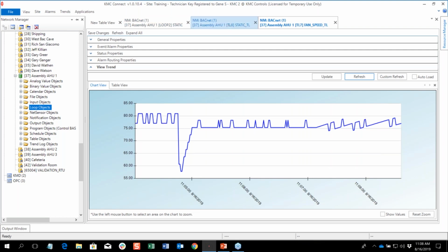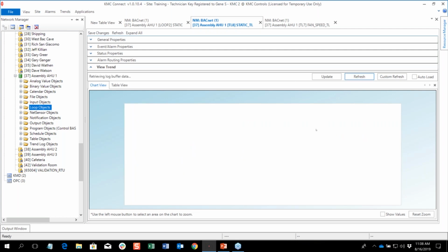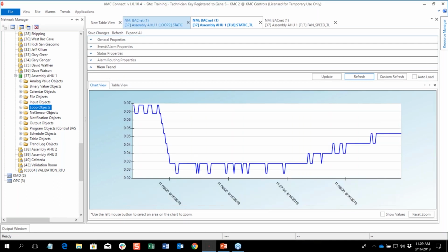So your proportional only valve is sitting there at just a quarter open, and everything is equal. You've equalized the loss with the gain. So now you actually want to get to set point. So you have to add a little integral in there to force that valve open a little bit more to raise the room temperature up to set point and then close the valve.